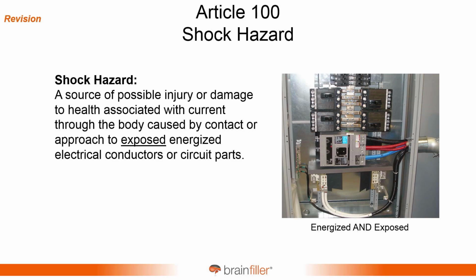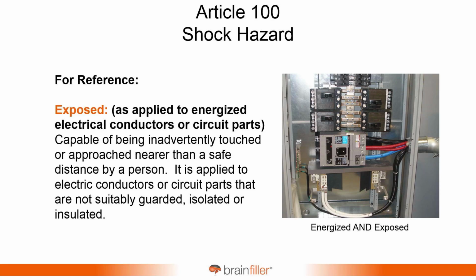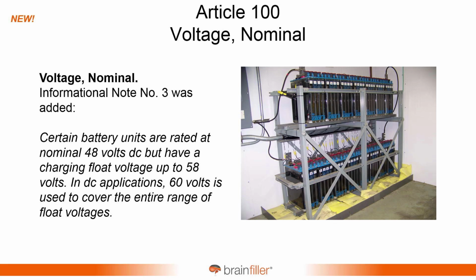The shock hazard, a minor modification with the shock hazard. The word exposed was added. And the word exposed is actually kind of important because somebody would walk by a panel and think, oh, does a shock hazard exist? I don't know. Do you have exposed energized conductors? So that word was added, and there actually is a reference that the word exposed is capable of being inadvertently touched or approached nearer than a safe distance by a person. So there is a reference to the word exposed.